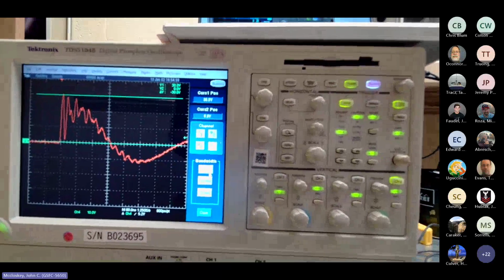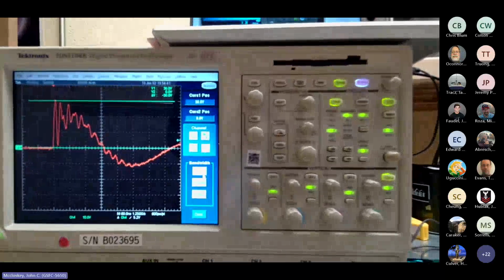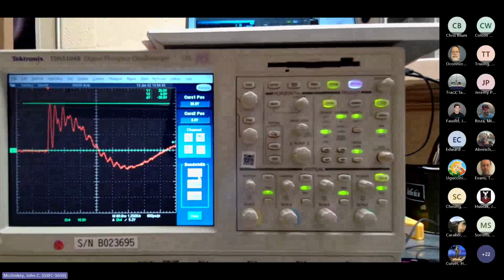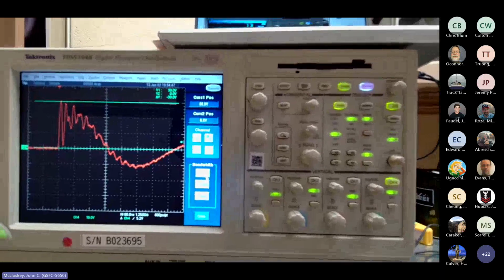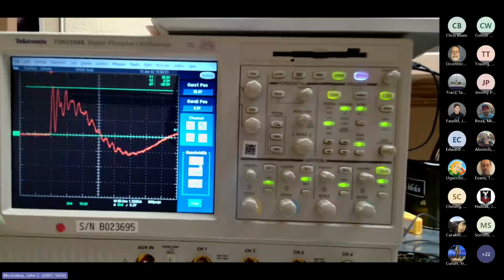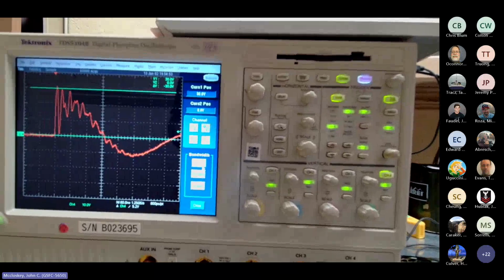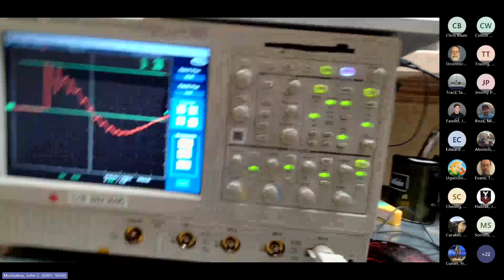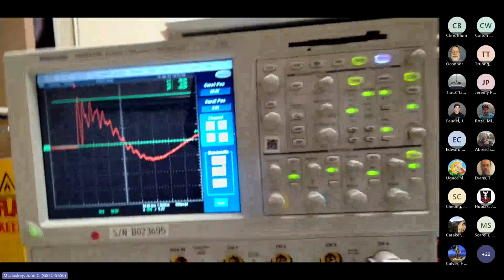We know that at least into the resistor pack plugged right into the unit, we have something of a cleaner waveform. This is what we're getting into the remote 5 ohms through longer wires, which is maybe more representative of what the EUT is going to see. And then you go from here and inject into the EUT.